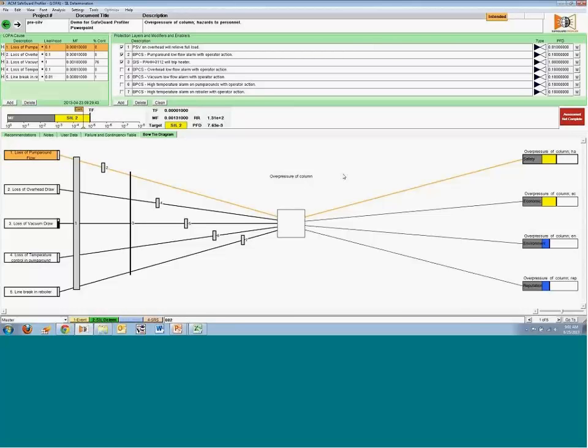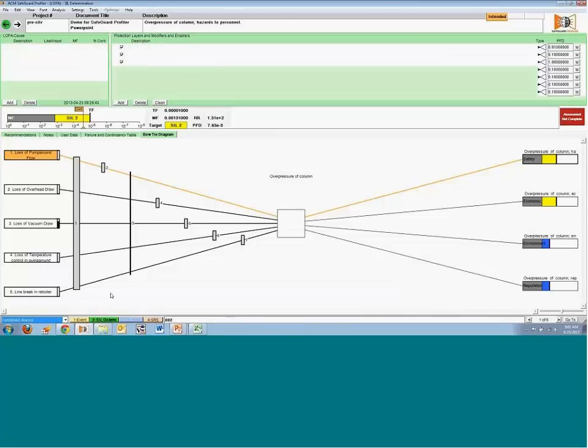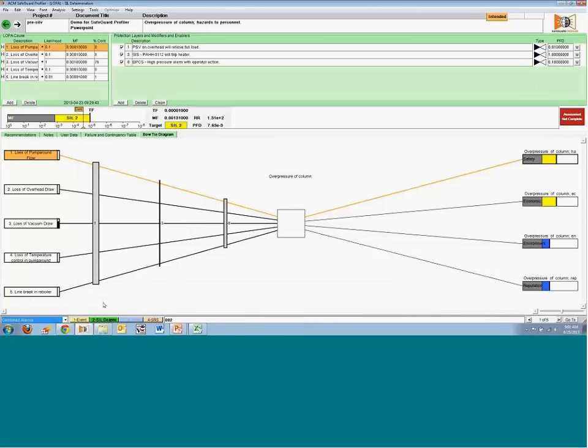If you just need the visualization, which is typically what the LOPA participants are going to be doing, you can look down here. The first thing we're going to do is combine the alarms together. I mentioned that earlier. So I've moved from having 5 separate alarms to just one single alarm that's going to cover all of them, the high pressure alarm with operator action. It hasn't affected our LOPA graph, which is okay, but we've much simplified the bow tie. So this is a nice, clean looking bow tie. This is what you want out of a LOPA. That means you don't have excess instrumentation.